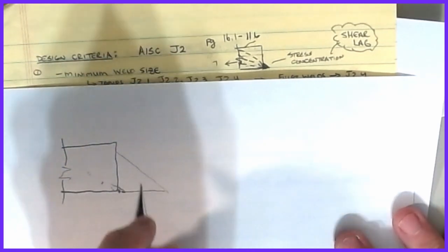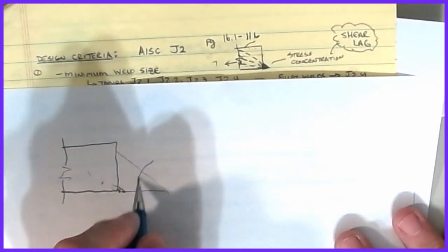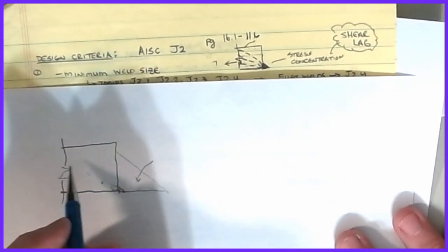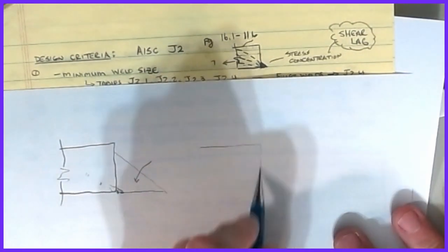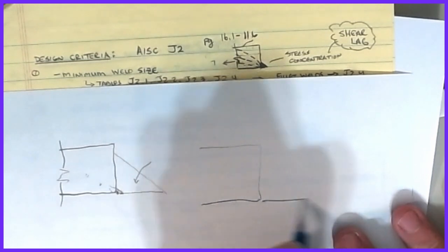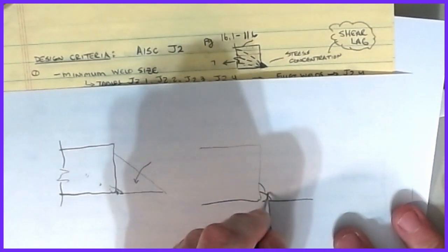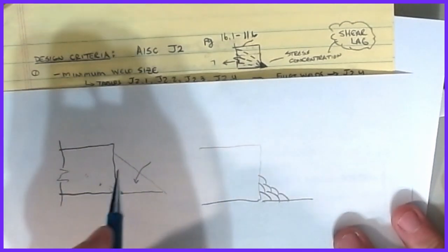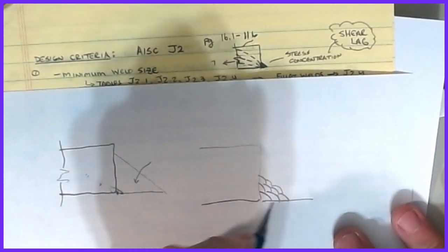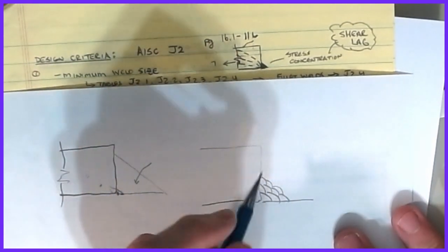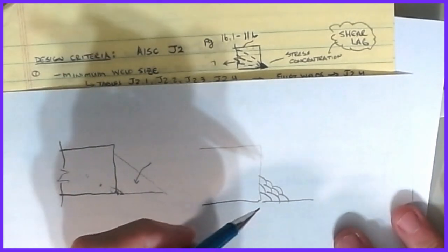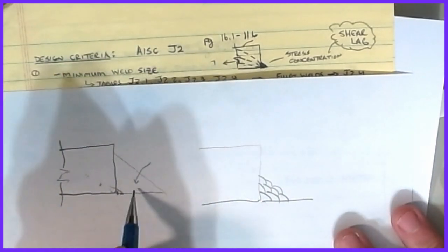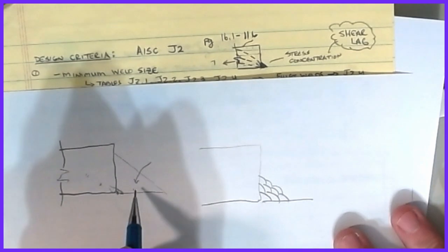Now, often we like to do this: if the plates are small, I can do this in one pass. But if the plates become really, really big, sometimes I'm forced to do multiple passes and start to build this thing up through multiple passes. And every pass you make takes time. And as they say, time is money. So we try to size a weld so that I can do it in a single pass, maybe two.